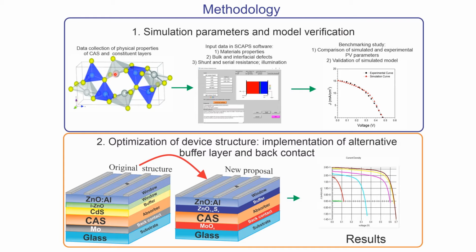Now we have here our methodology, and SCAPS-1D needs several material parameters for each layer. In order to make our simulation as realistic as possible, we took into consideration all information about the absorber layer given by the authors of the experimental cells, properties like band gaps, thickness, absorber density, and a buffer layer higher doped than the absorber layer, for example.